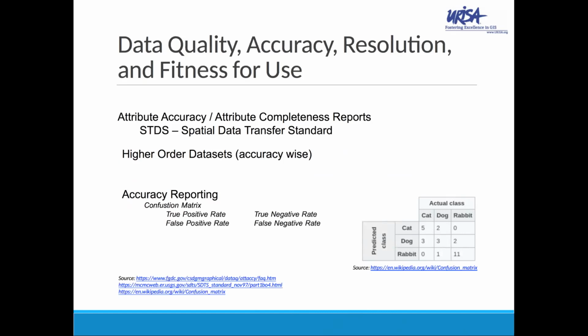Generally, you don't use this to say whether or not something is in the wrong spot. When we're looking at horizontal accuracy or vertical accuracy, you give that as an E95 or an E85, some other error ratio, and when looking at attributes, you end up reporting them this way. You will see this a lot with computer vision and raster processing. You'll see this with land use, land classification, automatic detection of features. You'll see those sorts of things appear here.